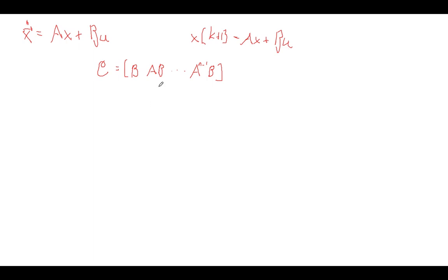And it's a numerical tool. You look at the rank of this matrix, and if it's full rank, then your system's controllable, and if it's not full rank, it's not controllable. But it's very binary in that way. You get a yes or no answer about controllability without really much intuition about what's going on inside. Now, we've also learned about the Jordan form of equations and how important the Jordan form is.